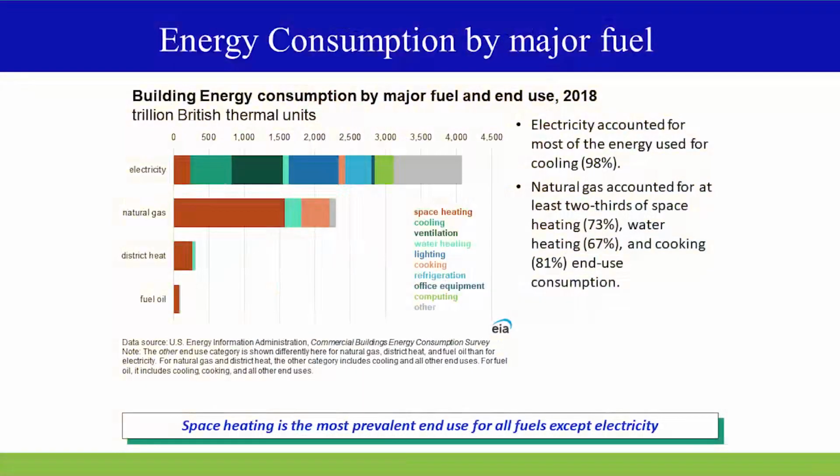If you look at the energy itself by end use, heating is the most significant energy use. That's about 32%, and some of the other significant ones are ventilation, lighting, cooling, and cooking. And also there are some process systems that may increase the energy consumption, but this is in general commercial buildings.